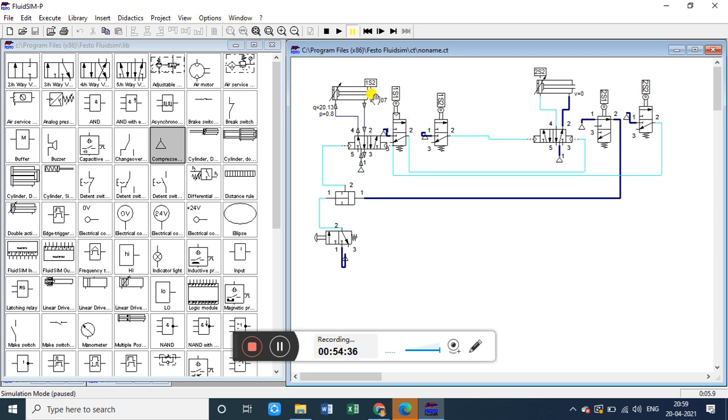Yes, this piston has left the 1s1 position, so 1s1 is getting unpressed. Because of that, this lower side block is in active condition now, and on the next click 1s2 will get pressed.